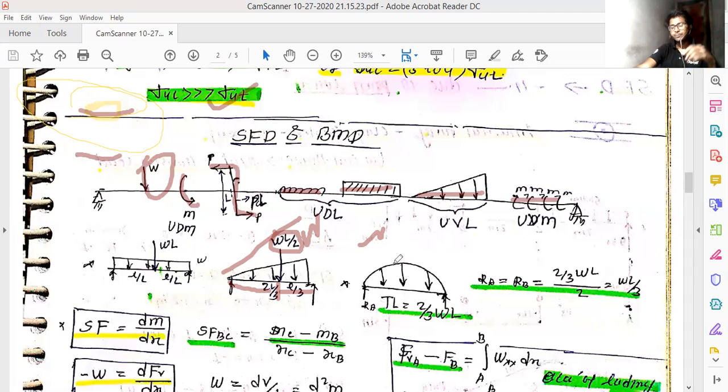So it is simply supported, and it is a semicircular kind of load, uniformly varying. You can find it with integration, but I am going to use the total magnitude acting on it, which is 2 by 3 times the weight into the length of that cross section. Just keep in mind that most of the time they play with the units of these two quantities, length as well as weight. So take a pause and verify the units they have given and what they asked.